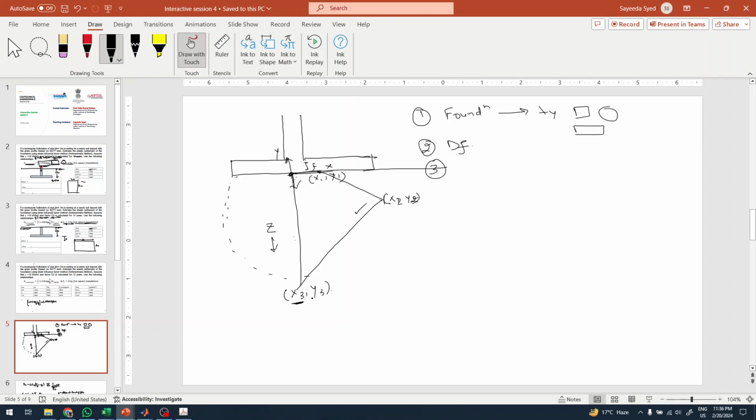X will be 0 here. So, okay, and now we have this plane. Now we superimpose our layers over this diagram. For example, this is my strata. It has these three layers. And at the center of each layer, we calculate this Iz value.